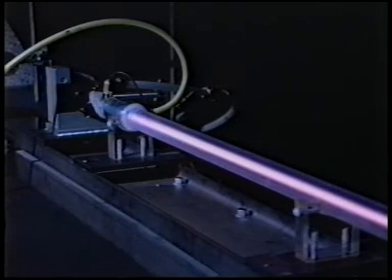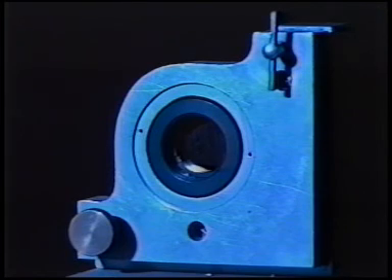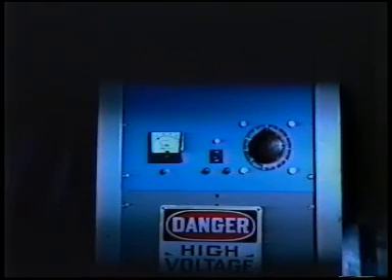The CO2 laser consists of a long discharge tube filled with a low-pressure gas. A 100% reflective mirror is placed at one end of the discharge tube, while an 80% reflective mirror is placed at the other end. Energy is put into the system by means of a high voltage applied to the ends of the tube. Cooling water is circulated around the outside of the discharge tube in order to maintain a moderate temperature.